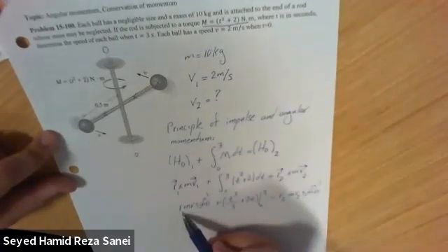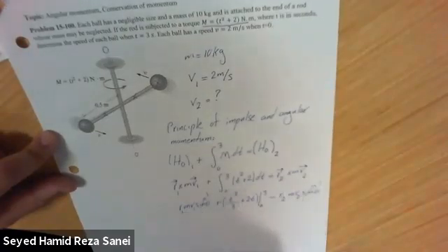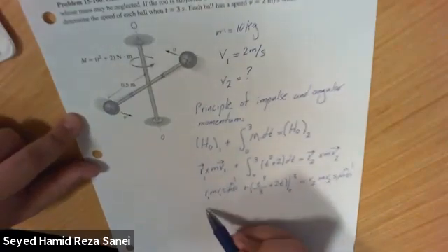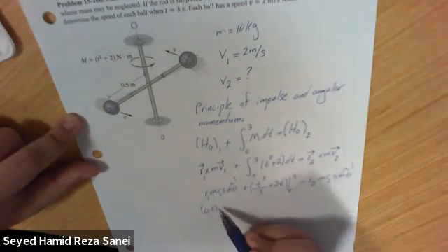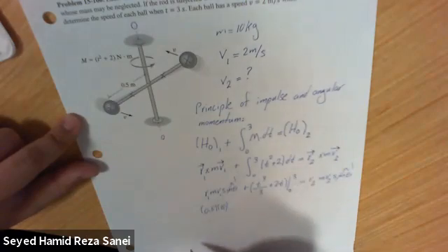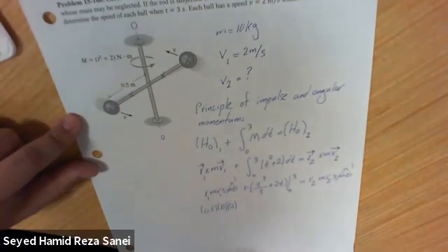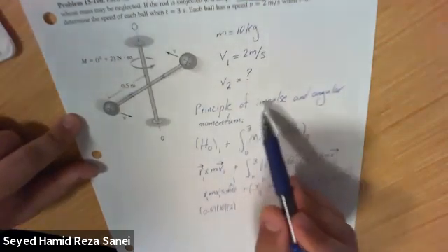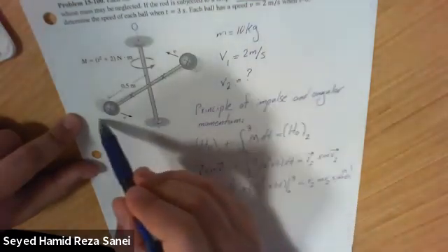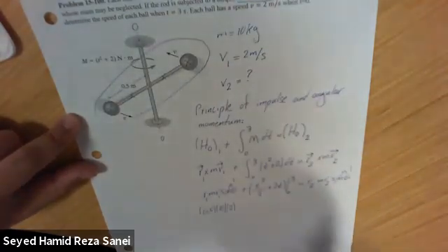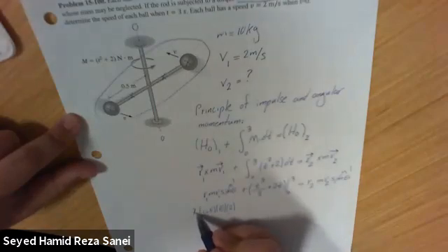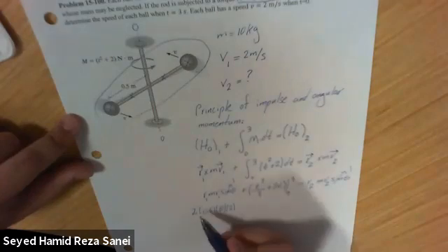So we're just going to plug in the values. Let me write the sub indices as well. So r1 is 0.5, is not changing. I have the mass, which for this case is 10. The velocity, which is given as 2, the initial velocity. And here, one thing that we need to be careful is that we are writing the principle of impulse and angular momentum for the whole system. So for the whole system, we have 2 masses, so we have to write 2 here as well.